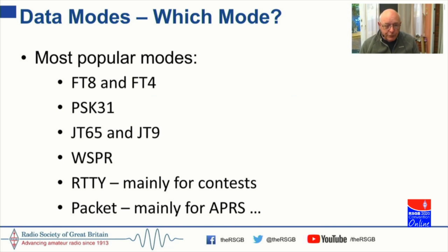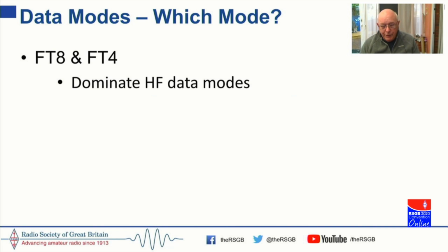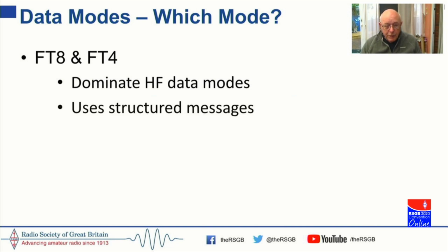I'll just run through those briefly so you can understand a little bit more about them and where they might be appropriate. So FT8 and FT4 have dominated since their introduction in 2017. They are by far the most used HF data modes programs. They use what are called structured messages. So it's a very rigid, fixed messaging system, and you basically only exchange your call sign, your locator, and signal reports. And there's only one small field where you can add a little bit of personalization, but you've only got 13 characters for that. So it's very much fixed